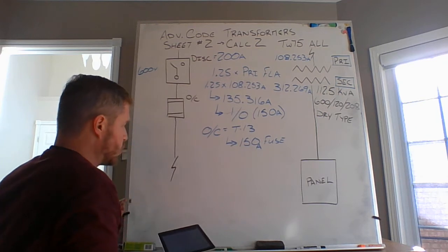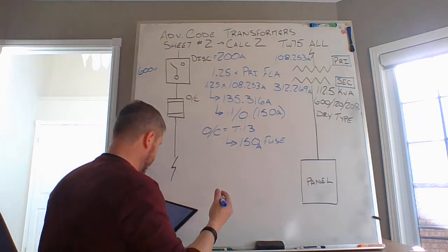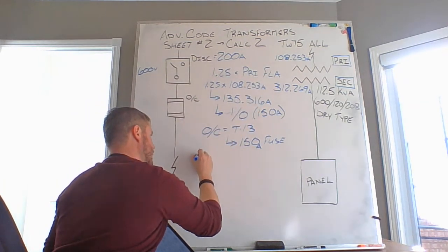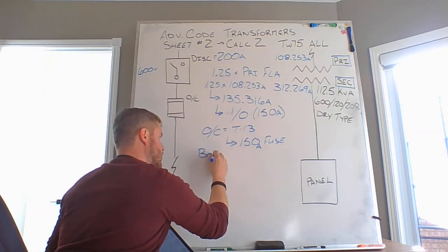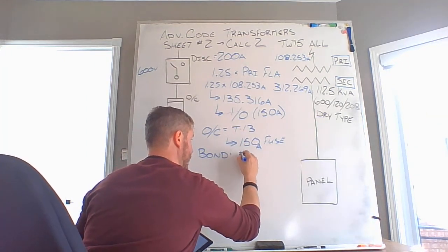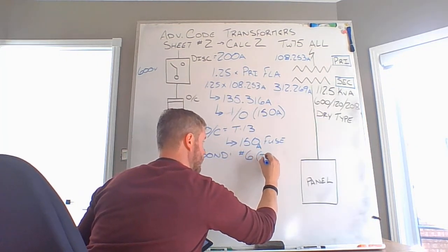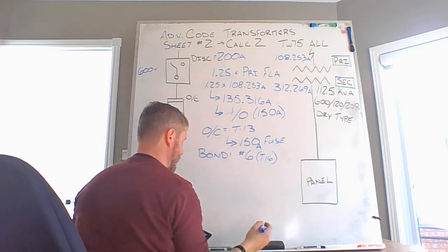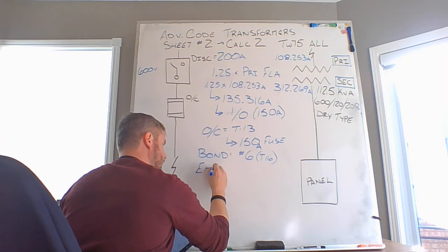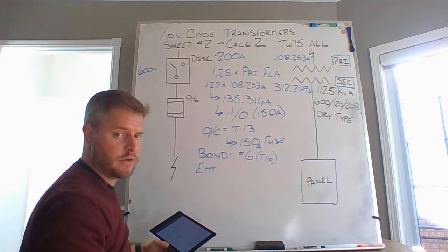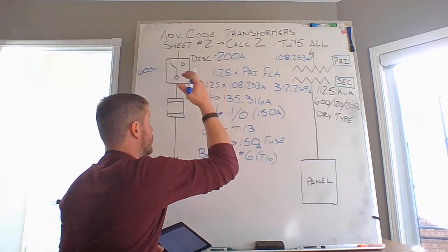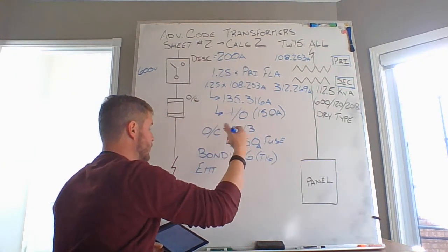Once again, I fully trust your abilities to do a conduit fill calculation. Also incorporating the bonding conductor that we need for this installation, being a number 6. Coming from table 16. Okay. The minimum size EMT that you're required for that installation, once again, coming from the sheets that are available for you on Fanshawe Online, transformer sheet number 2, calc number 2.